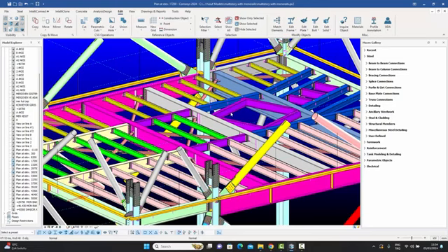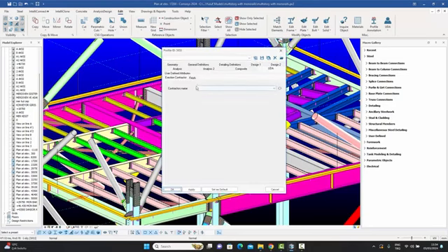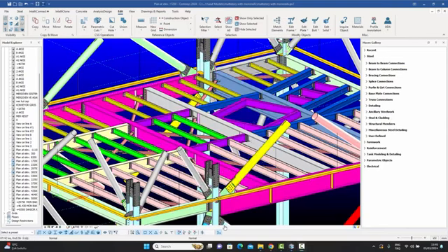And if I were to now double click on this beam over here, you will see that now we have two tabs over here. One is the erection contractor tab, which wasn't there before because I hadn't added it, and the finish one. And the finish one now has two user-defined attributes under it. And like I said, you can have as many as you want. You can have 10 different variables over here. You can have 10 different tabs towards the side, as many as your project basically requires. And you can then use them in different parts of the software.